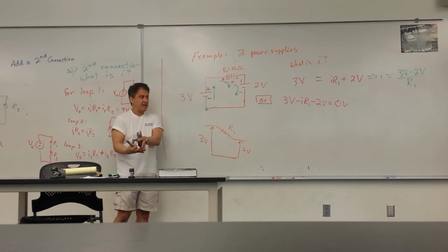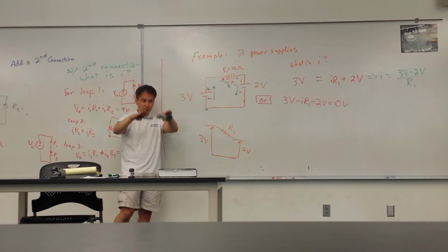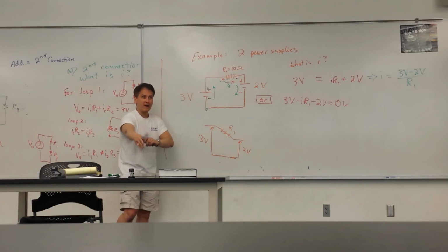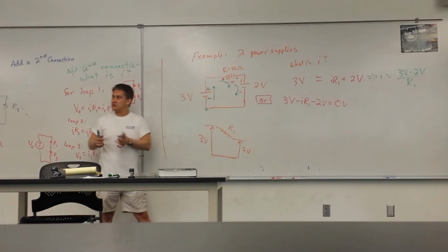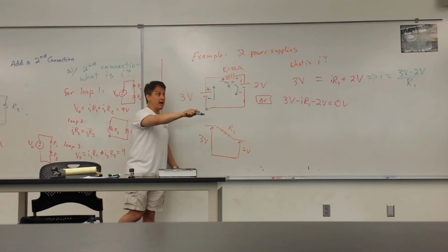Why can you only draw so much energy? Two reasons. One is that with any chemical reaction, there's always a limit to how fast it's going to run. And that limit will depend, among other things, on the quantity of the substrates involved. The more reactants you have, the higher the probability they'll chemically react, the faster you'll get product formation and electrons out. When you deplete your quantities, you're spacing out the chemicals that are reacting, and you're slowing down the reaction process itself, which limits the amount of current that you can draw out, which looks effectively like a resistance inside the battery. We're not quite to that point yet, but that is what we're going to be building to next.